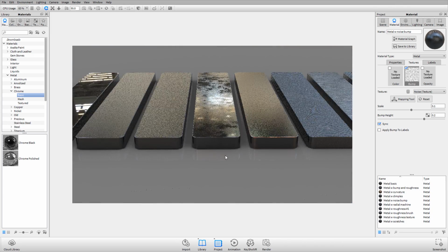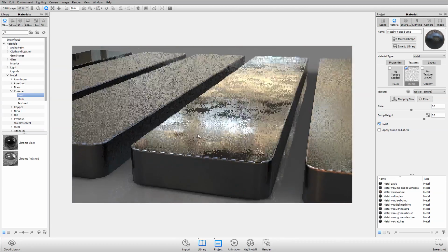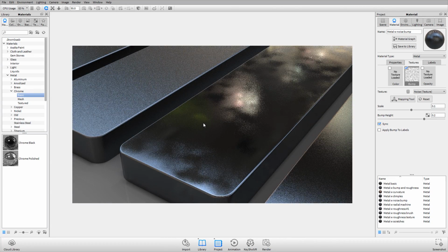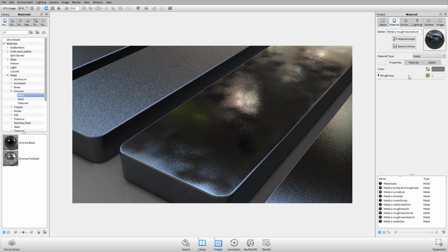All right, our fourth little part right here, this is going to get us into a really interesting category of textures, and actually a new texture type for KeyShot 6. So if I double click on this material, you'll notice that I've got my color still 50%, but now the roughness icon has changed and my slider has gone away.